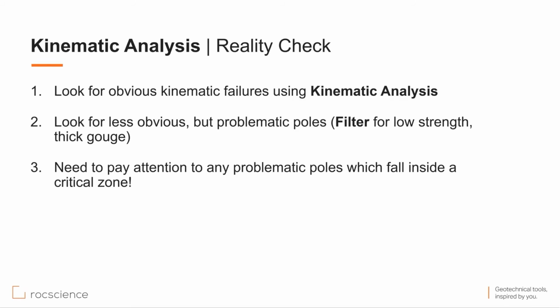And finally, we perform further kinematic analysis in DIPS to see if these happen to fall within a critical zone. So in this case, we checked the daylight envelope for planar sliding. And despite being few in number again, we definitely need to pay attention to any of these poles that fall inside that daylight envelope.